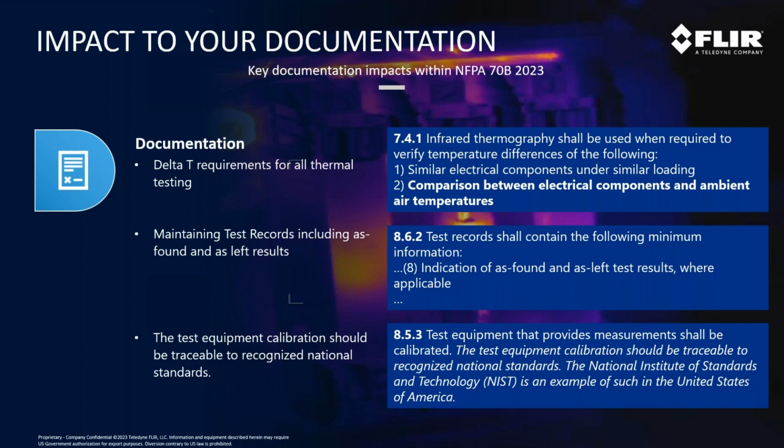Another question I get here all the time as well is, in the past, we've only documented issues, right? We've only documented problems with thermography. We're going out, we're doing our scanning like NFPA says we should. We're being good stewards of our assets, but from a reporting perspective, we're not really documenting things that are fine, that are okay. Well, that's no longer really the case here. You really do need to document all of those assets over time so that you can make sure that you're trending and tracking that information in an appropriate way.